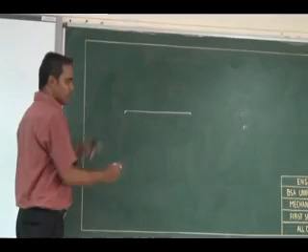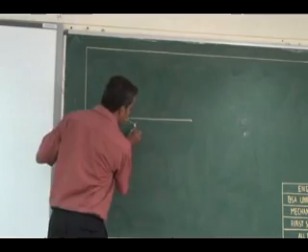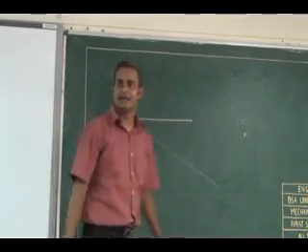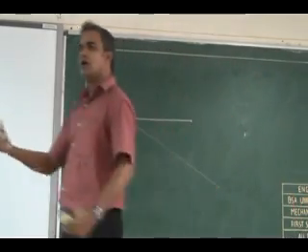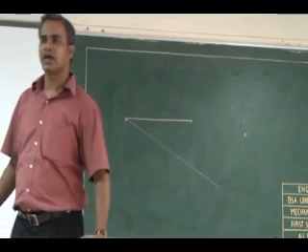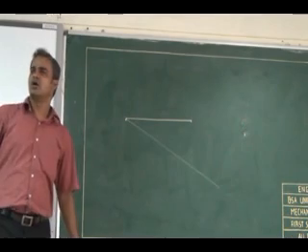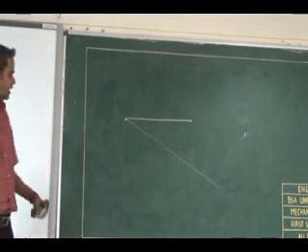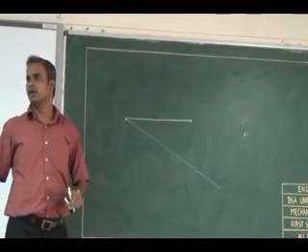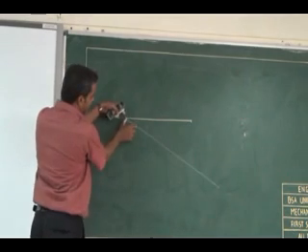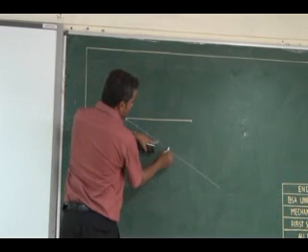See what I can do. I can take any arbitrary angle. It is a construction procedure. I can draw a slant line. Along this slant line, I take an arbitrary measurement in my compass, say 10 mm. No need for exactly 10 mm; it can be 15 mm. On the inclined construction line I have drawn, with that same measurement I can cut 9 equal divisions.